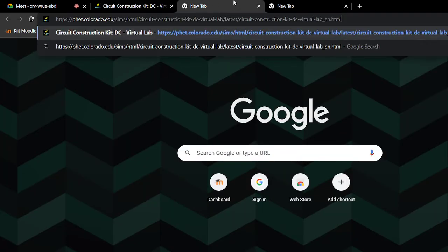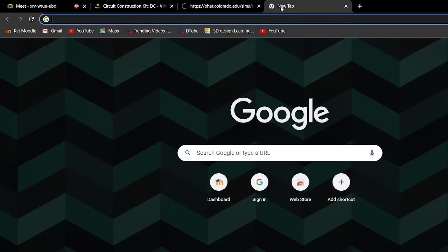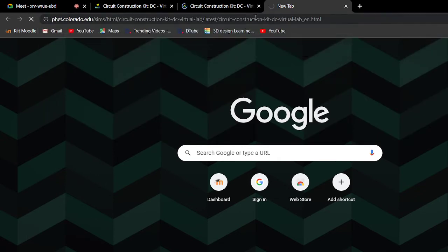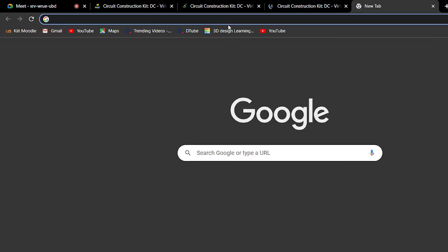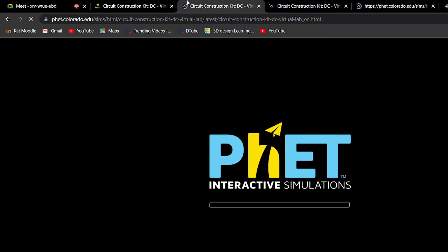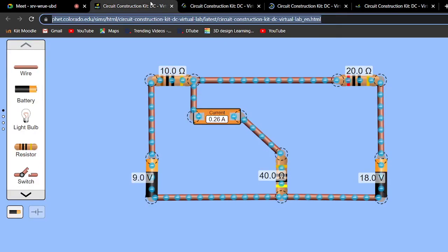You will verify that Thevenin's theorem is verified. Your objective is to verify Thevenin's theorem. How will you verify it? Offline, you have to calculate with pen and paper what is the current in that particular branch. Then you use the simulation platform and see what is the current. Check whether both the currents are equal or not.